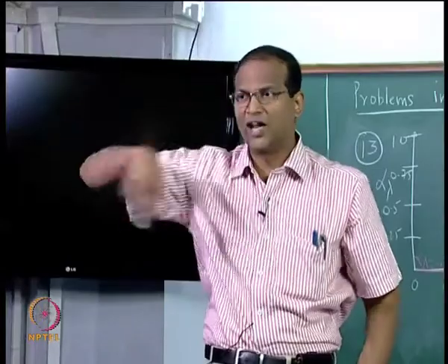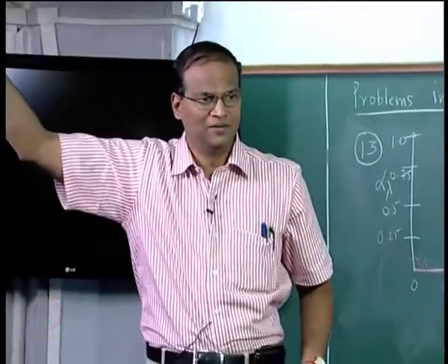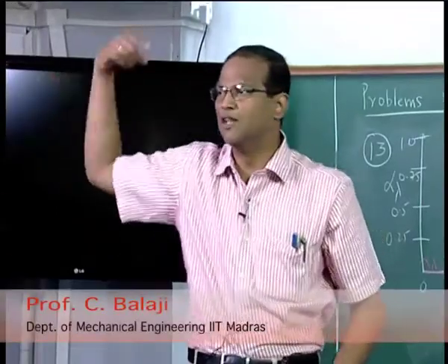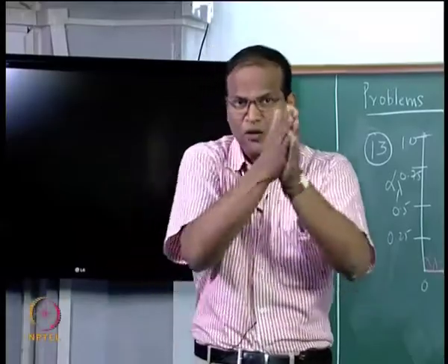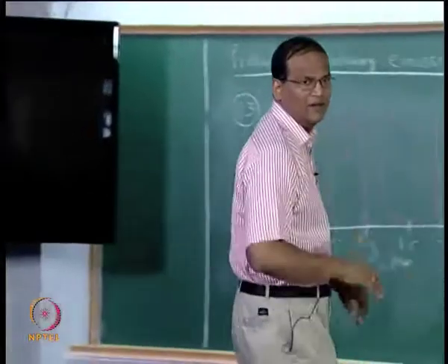Then you have to again use the F function chart with 120 degree centigrade and calculate the epsilon, and then epsilon sigma T to the power of 4 will be the emissive power, then the third part will be this. So it is not easy, when I give solar absorptivity 15 minutes it will take for you to solve the problem. Yeah, just start.